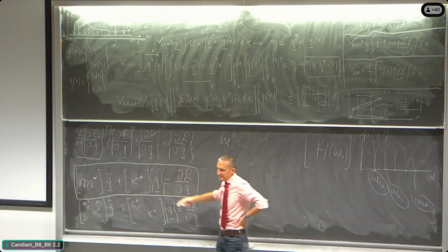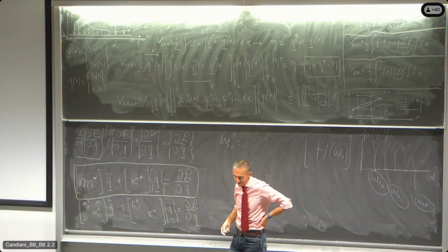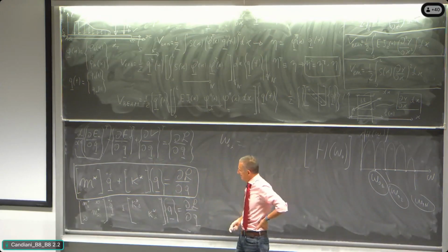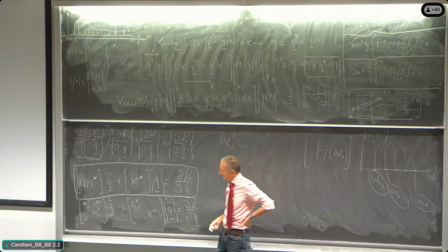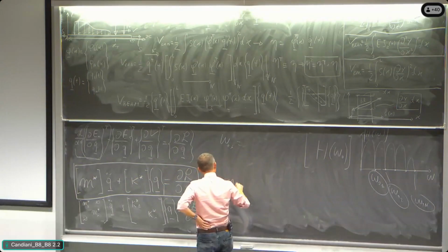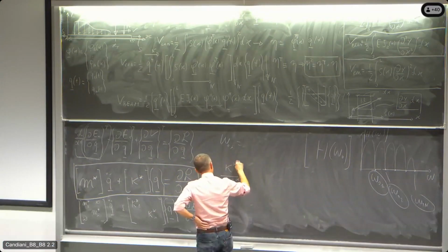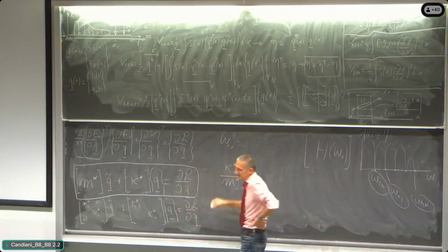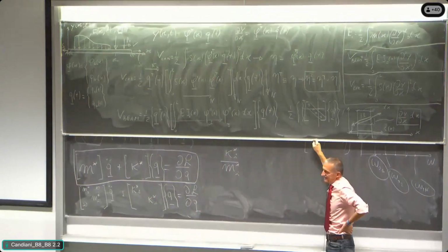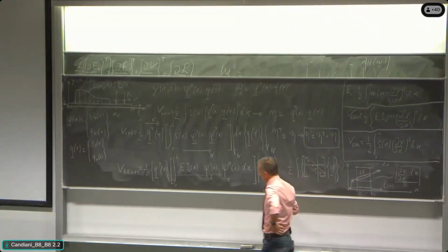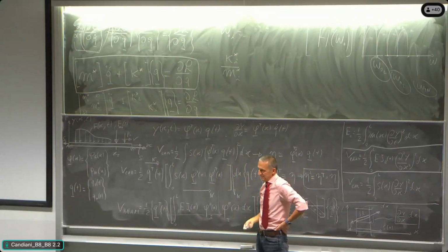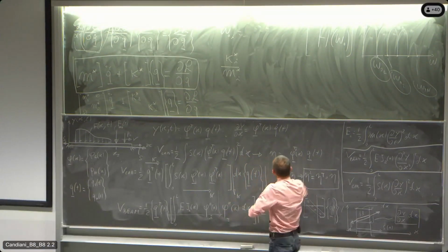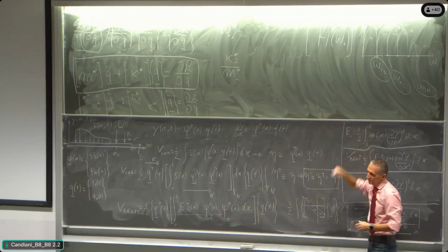Well, here you calculated the mass matrix of mode i, you calculated the modal mass of mode i, and you calculated the modal stiffness of mode i. You did those calculations in a totally different way, a procedure that has nothing to do with this null determinant.